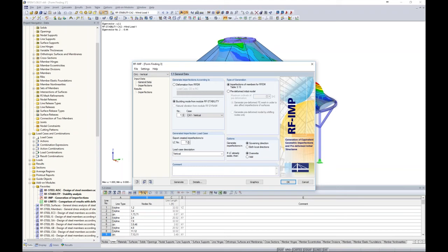It's certainly important in Eurocode, as the Eurocode calls for imperfections within all of our load combinations. AISC is not so straightforward with that. It really depends on some different factors, but regardless, it can be applied for all design no matter which standard you're looking at.